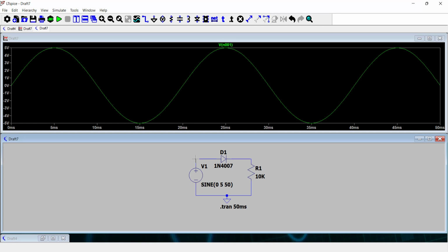Now, what is the rectified signal? So the rectified signal is the voltage I get after the diode. So should I place now my voltage probe at this side? I will get the voltage after the current has been rectified, and let me do that.